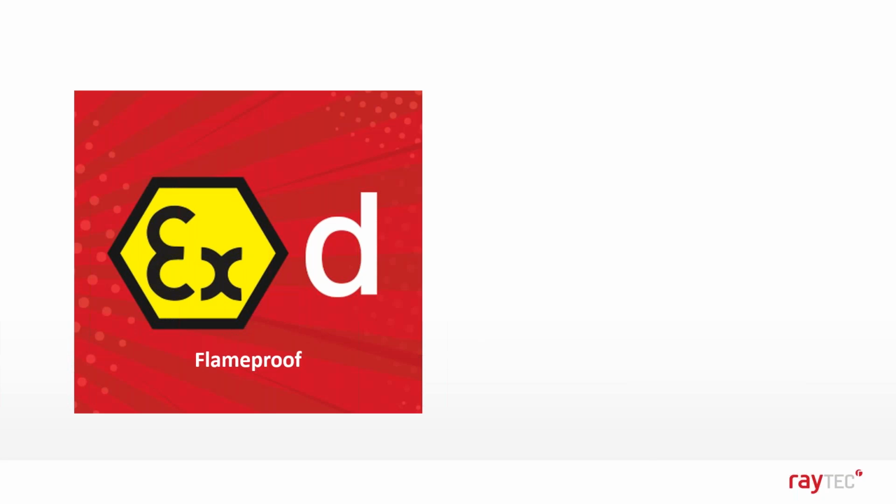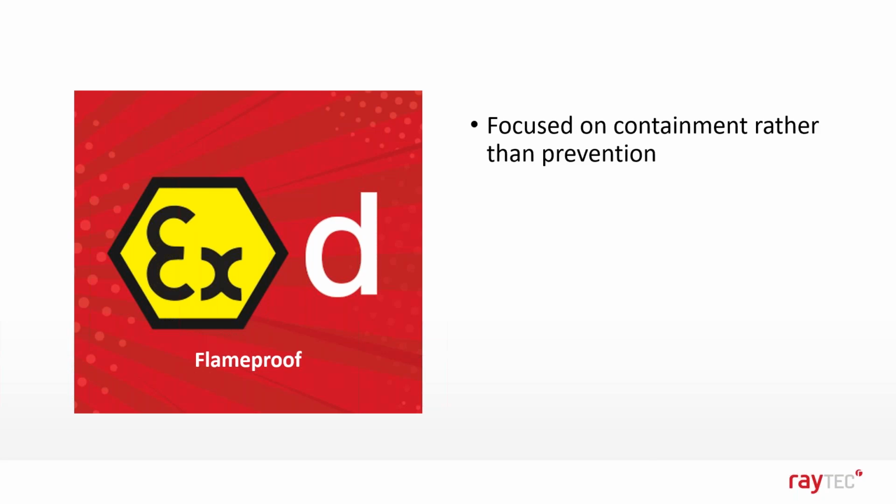Now let's talk a little bit about the other protection method that we'll be covering today, EXD. The EXD protection is commonly referred to as flameproof. In contrast to the EXE luminaire, which is designed to prevent an ignition source from occurring, this protection method is focused on containment, to contain the explosion within the housing of the luminaire so it cannot escape into the hazardous environment outside.